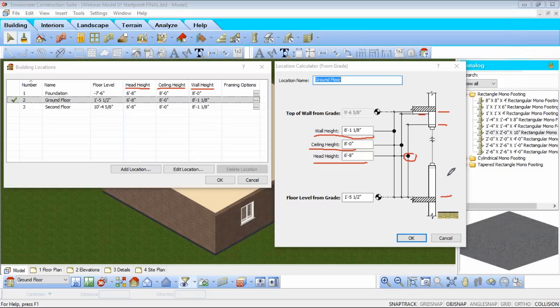And you'll note that the wall height is independent of and often different than the ceiling height. And there's a reason for this. It allows for drop ceilings, or if you had strapping between your structural floor on the level above and the finished ceiling for that level. It also can account for any finished flooring material you may add on top of your subfloor. Because as we just learned about the floor level, this refers to the top of the structural floor, not the finished floor material.